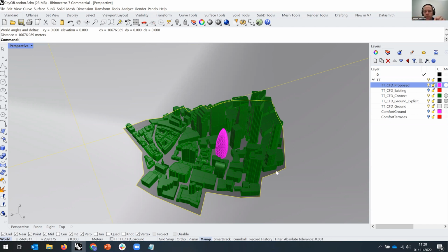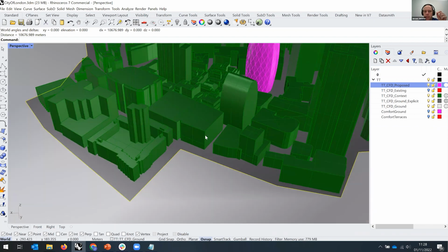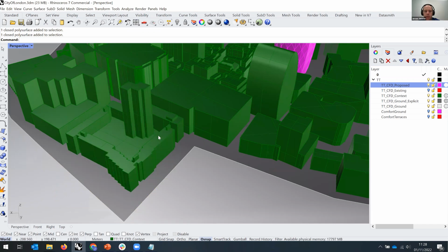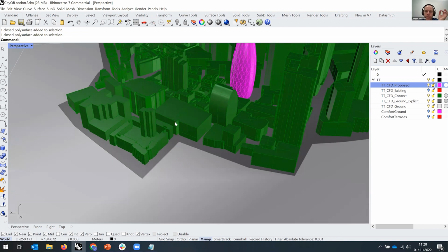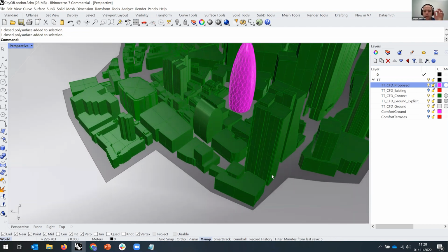If you're actually modeling the buildings to a certain level of detail, and it's not that deep, right? You see they're relatively simple extrusions. So I'd say a step size of 30, 50 centimeters, so 1-2 foot. That's the type of thing I typically include in the surrounding buildings. The building itself typically is a bit more detailed. But with those buildings modeled, it doesn't make sense to attach that atmospheric roughness to the ground surface within that, because you've covered that already. So most of the time I split it up into 2 ground surfaces, and the one in the middle is called ground_explicit.